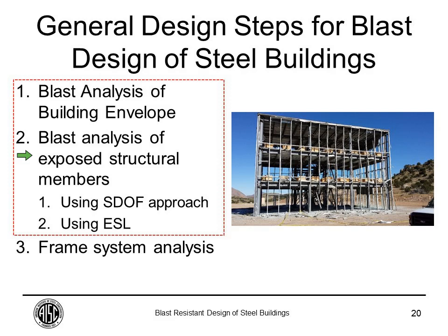Because as we're going to see, we have a few illustrations later in the slides, a lot of the members end up being protected by the envelope. So generally, your exposed members are going to be in the roof area, and sometimes if you have some spandrel beams or perimeter beams that are providing support to curtain walls, you need to look at those too. And in some cases, it's not very common actually, you may need to look at a column design.